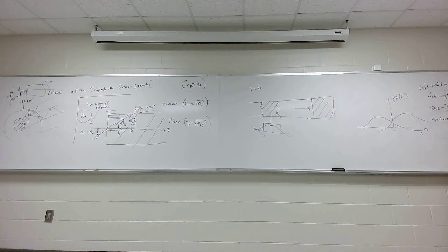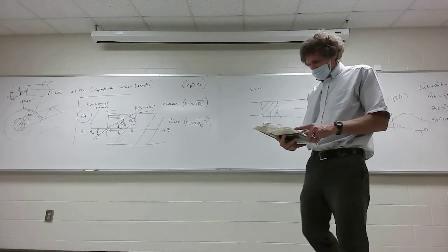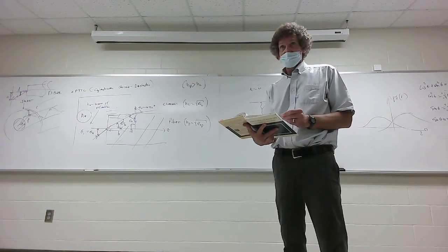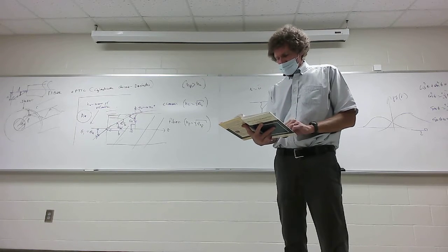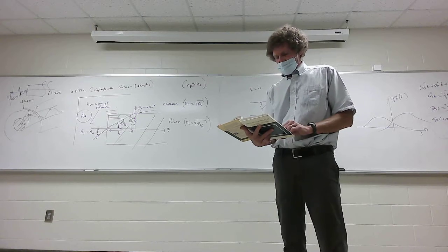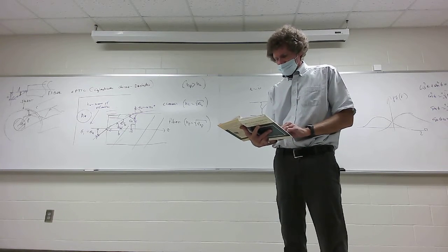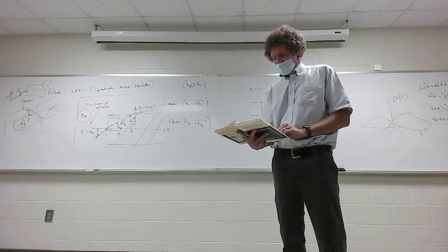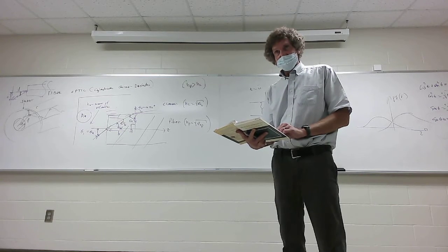But in his book, he does do one thing that I want to share with you. I don't get into this, but if you have your books on page 408, without an explanation, because this has to do with the solution of Maxwell's equations for cylindrical coordinates, he gives you an equation for step index mode. That's the type of fiber we are talking about. How many propagating modes will be present? This is equation 7.104, and he talks about a cutoff wavelength,